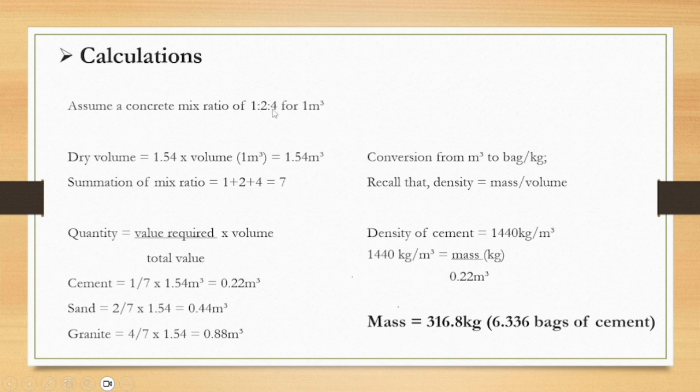So for this work, I'm going to need, for this work 124 and the quantification is 1 meter cube, I'm going to need 6.4 bags of cement for the job. If I'm not adding any waste, let's assume I won't have any waste, I'll be having 6.4 bags of cement for the job. Now, that is for cement.